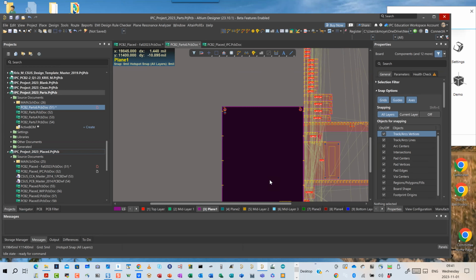We also have certain manufacturing minimums similar to minimum trace width, minimum copper clearances based off of copper weight, but even beyond copper weight for the layer, for plane layers, the fabricators do tend to like a slightly larger minimum clearance definition compared to what they're willing to do on a signal layer.